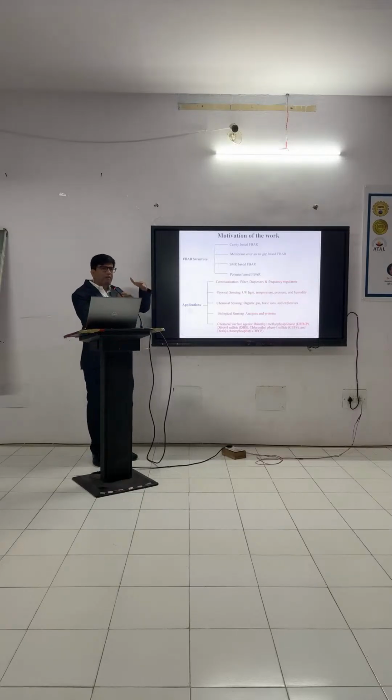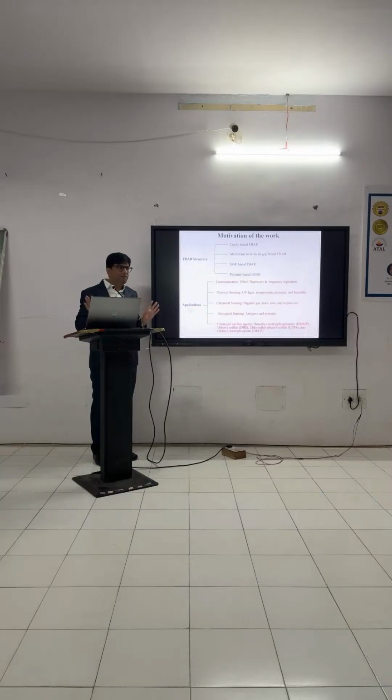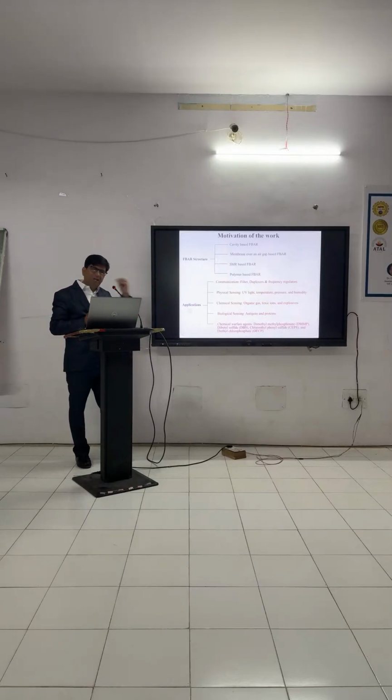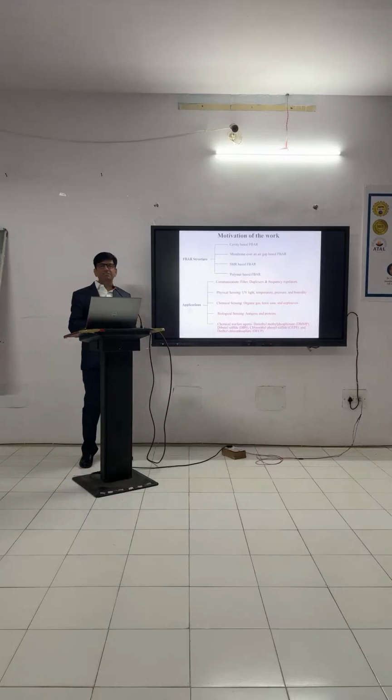Because anyhow I have to keep my acoustic signal moving within the piezoelectric layer only. Otherwise, what will happen? Your acoustic signal will penetrate into the silicon substrate and will vanish. There will be no more generation of acoustic signals. Clear? Then we have different kinds of applications. Why is this device important? Because it will help you to think about your PhD also.